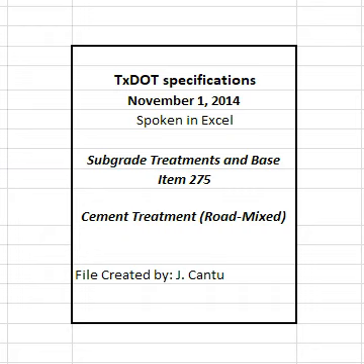2.6 Mix design. The engineer will determine the target cement content and optimum moisture content to produce a stabilized mixture that meets the strength requirements shown on the plans. The mix will be designed in accordance with TEX 120E or will be based on prior experience with the project materials. The contractor may propose a mix design developed in accordance with TEX 120E to meet strength requirements when shown on the plans. The engineer will use TEX 120E to verify the contractor's proposed mix design before acceptance.